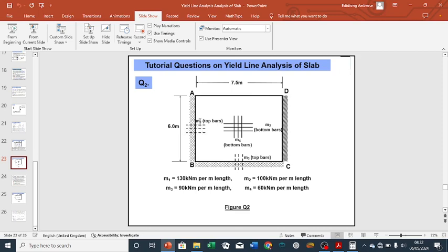The top reinforcement here, M1, these are top bars M1. Look at the direction. The reinforcement is perpendicular to the continuous edge. And we also have top reinforcement M3 on this other continuous edge, while you have span reinforcement here, vertical and horizontal direction, which will be the main and distribution span reinforcement, M2 and M4.